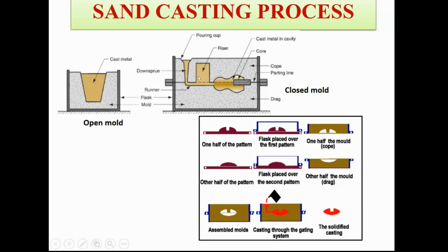Here is a cavity which is known as the riser, and this is also known as the reservoir of your casting. Your molten metal flows and reaches the entry of your mold cavity. This particular section is sometimes known as the gate. The gate is an opening through which your molten metal enters the die cavity.